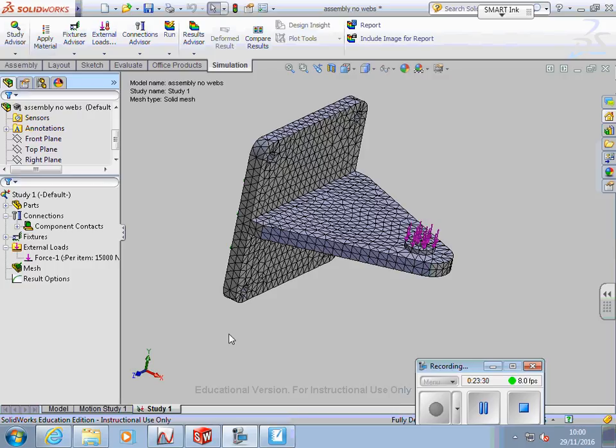There's another add-in called SolidWorks Flow Simulation. On the renewables module at level 6 at one time, they were doing some flow rates around aerofoils, and those simulations were taking over an hour to calculate. So you need to be careful; probably best to try a coarse mesh to start with, and then see if you need to modify it.